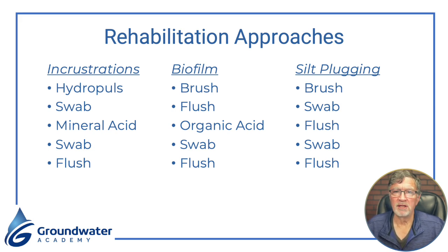Silt and clay plugging, you're going to go in and you're going to brush the well to clean the screens out so you can get access. And then it's going to be a lot of swabbing and flushing and trying to break up the silt and clay that's been plugged up in there and break up those sand bridges. And then finally, you're going to flush.